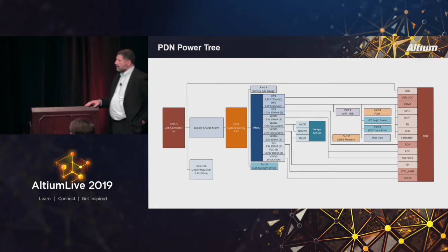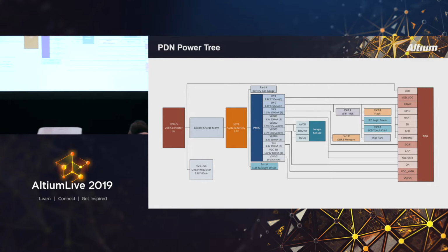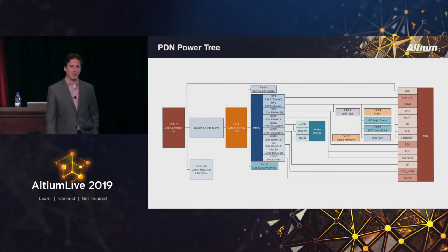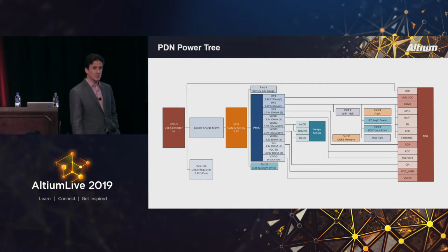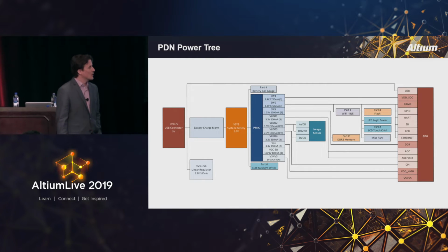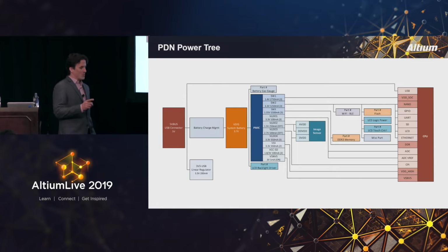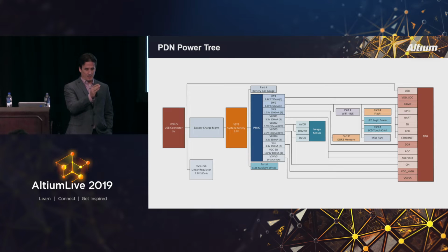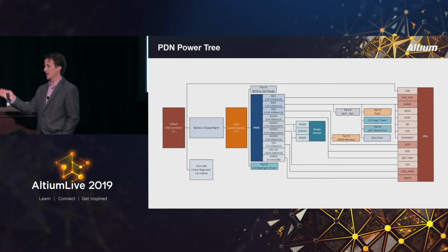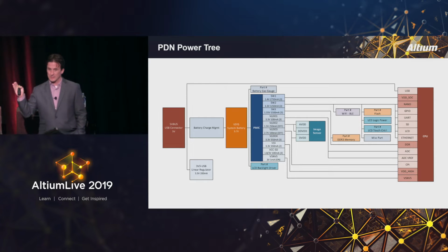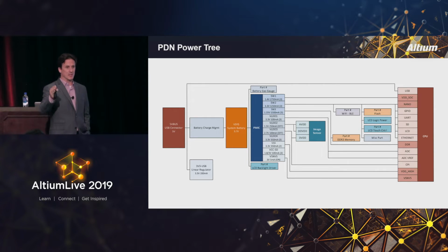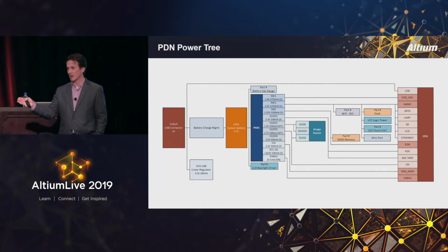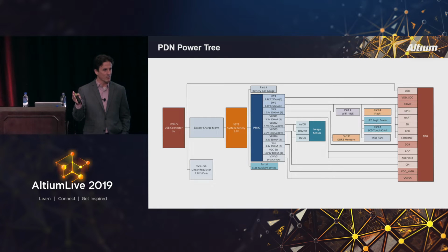One thing I would say about power delivery is that you've got EMI issues to consider, and switching power supplies usually end up being big contributors to noise on a circuit board. But what I would say, and I'm interested to get your feedback on this, is if I've got 20 watts coming into a board at 20 volts, and then I've got power conversion that steps that down, power is conserved except where it's lost in the power conversion.